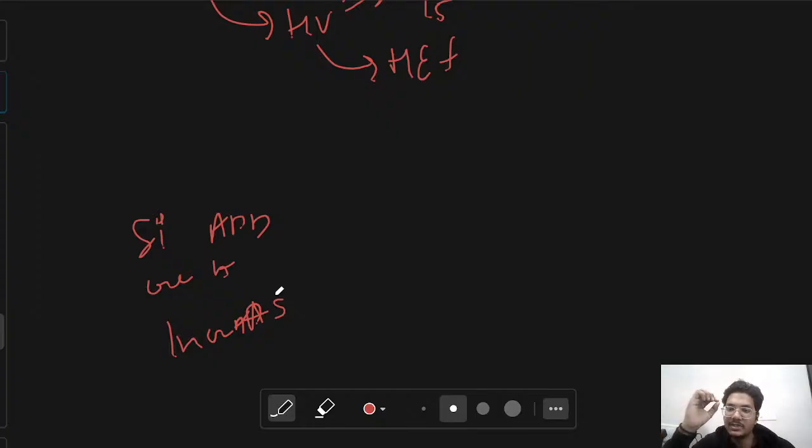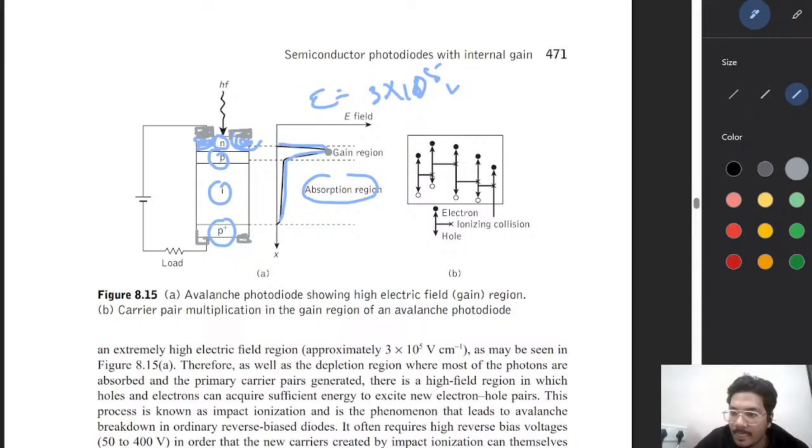To achieve high speed performance, the APD must be fully depleted in the absorption region. If carriers are generated in the undepleted region, they diffuse slowly and create a long diffusion tail, which slows down the response and decreases the high speed performance. Thus a strong high field is needed to make all carriers drift at saturation velocity.